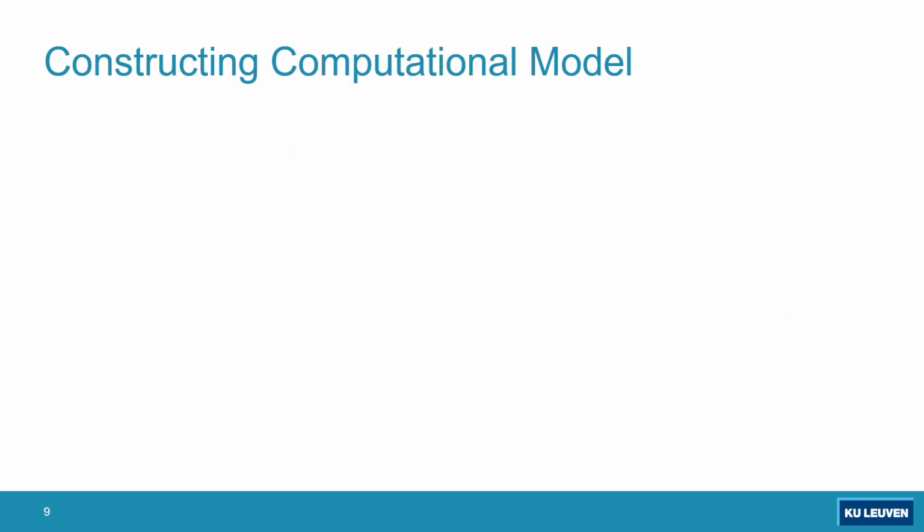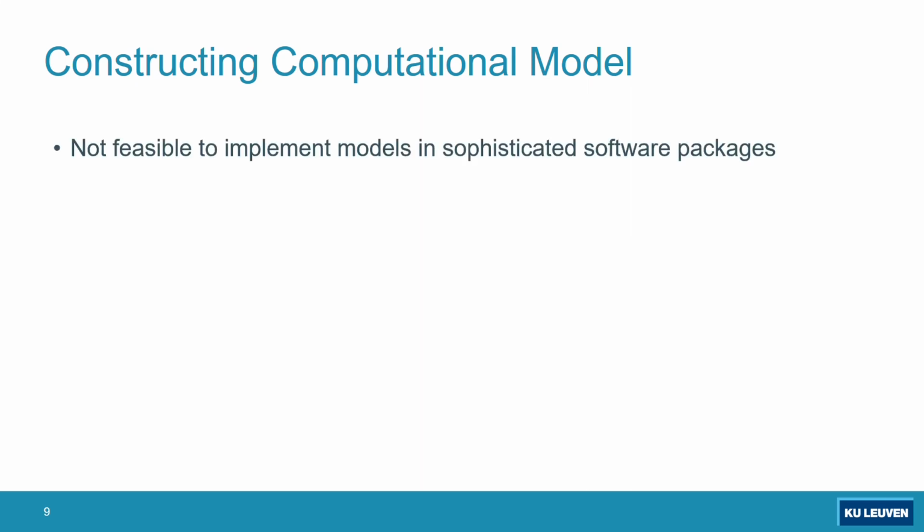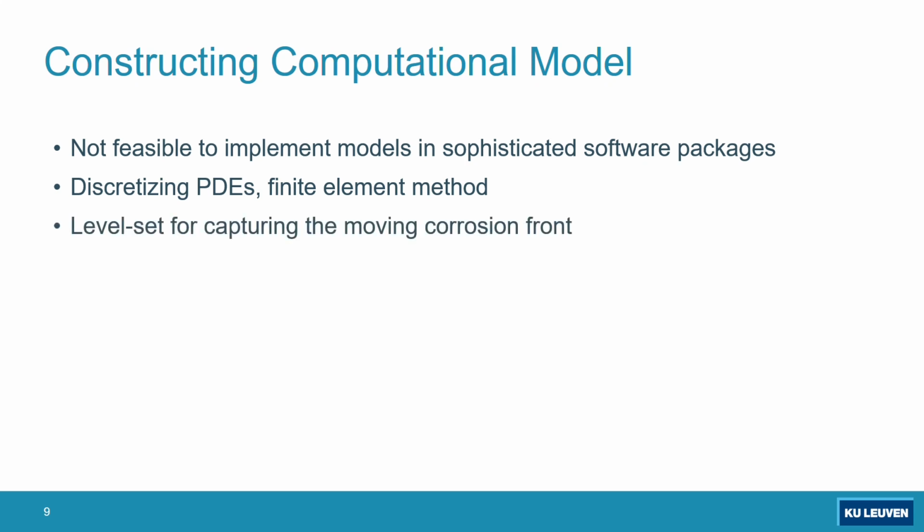It is very common to use software programs with pre-built models in tissue engineering and biomedical engineering, but in this case we cannot do that because we want to have full control, especially at the interface of the material and the surroundings. I will show you why. So we need to solve the equations ourselves by discretizing the PDEs using the finite element method and finite difference method, and we also need another technique to capture the interface movement, which is the interface of the implant as it evolves over time and shrinks because it's degrading.